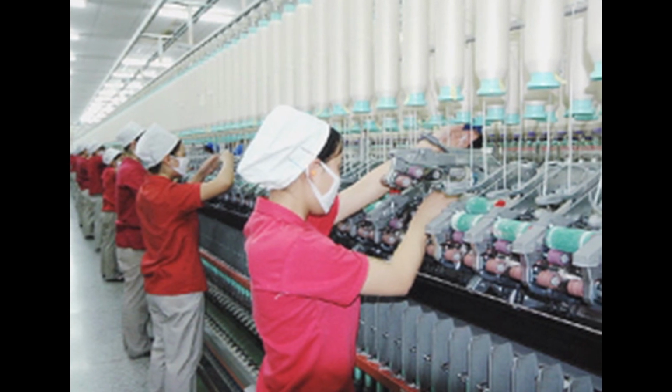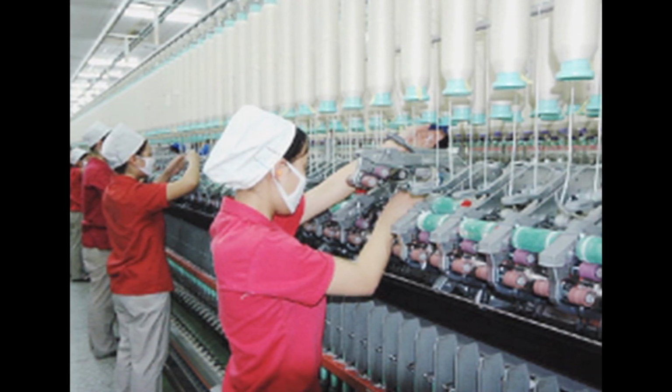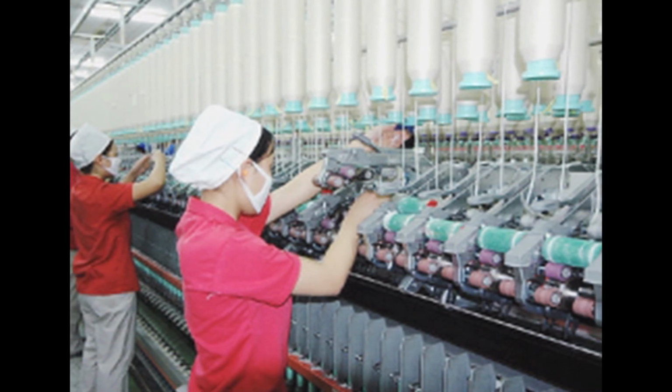And then an additive like anti-static agent is added in order to dissipate the static electricity that is produced. You know, polyester and other fibers which have very low absorbency cannot dissipate the electricity that is being produced, because static electricity is produced by rubbing the fabric against each other and against itself. And so the electricity, if it cannot be conducted away, will be stored on the fabric and creates a lot of trouble for stitching as well as for the wearer. These anti-static agents, when introduced into the filament, will be able to dissipate the electricity that is being produced and make the wearer comfortable.